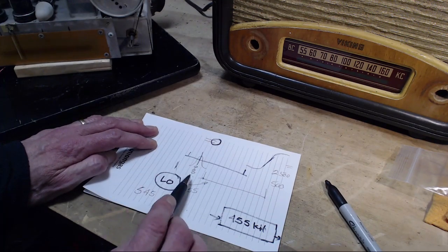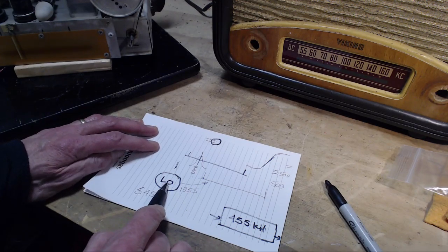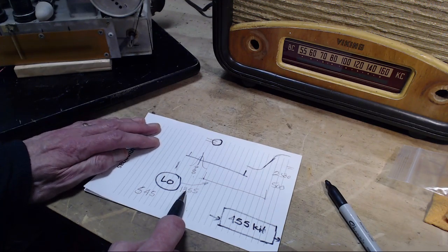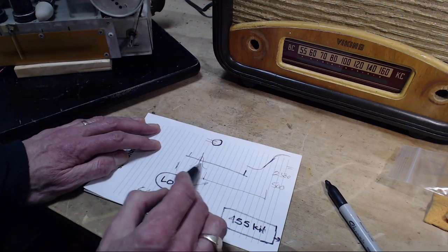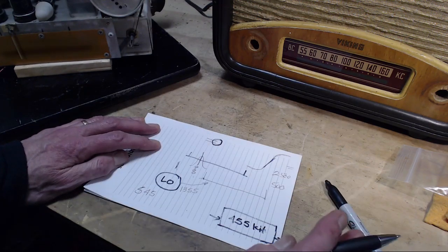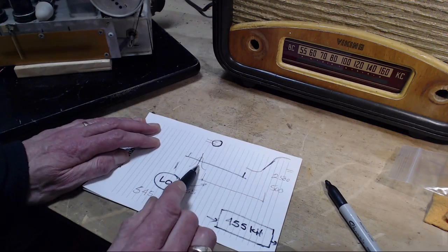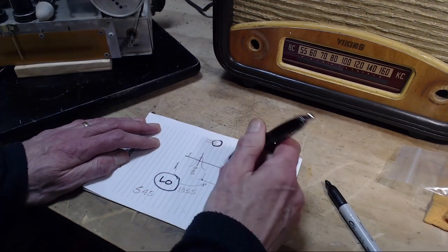Let's go back to trying to tune 900 with a high side local oscillator running at 1355. We can get another 455 signal out of this radio, an unintended one. If there's another signal out there in the world, really anything reaching the radio antenna, but another broadcast signal is what we're worried about, 455 kilohertz above this signal. It's another one up here.